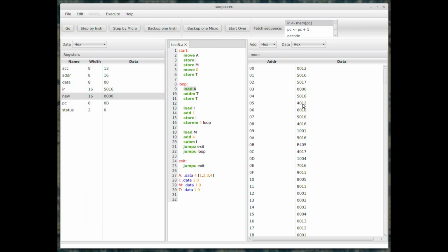That instruction is at address 5, so you can see load, and its previous value was 12. After I've executed that new store instruction, it will store the value 13 to the low byte, and to the high nibble of the high byte, the immediate value 4, which is the opcode for load. So we'll rewrite that load instruction, updating the address it will read. After that, you can see it will now read address 13, and address 13 is the next element in our array.